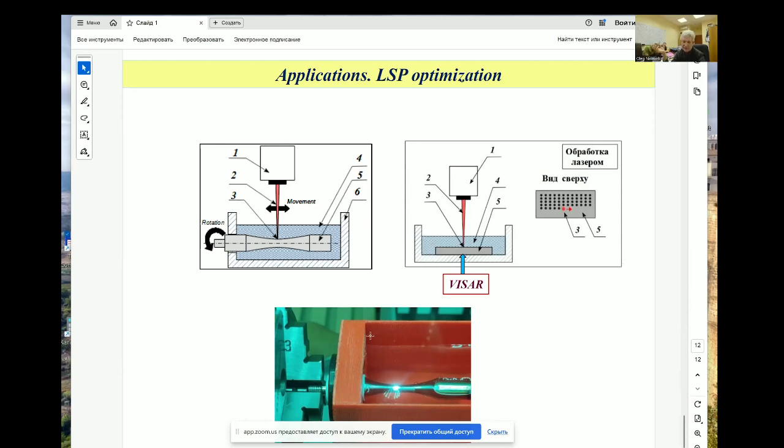And according to our feeling, if we need to estimate the realistic parameters of shockwave loading, it's really necessary to realize standard plate impact tests and to have a representative sample according to ASTM requirements and so on, to provide a fatigue test for the sample when all the volume is in conditions of shock wave loading.